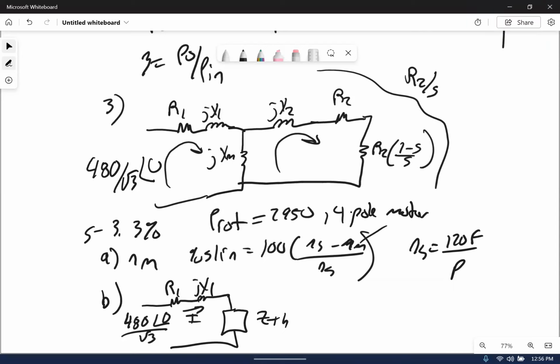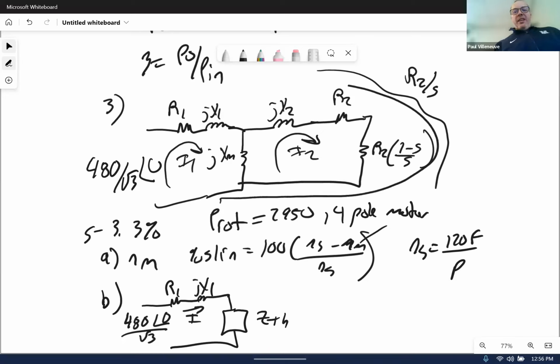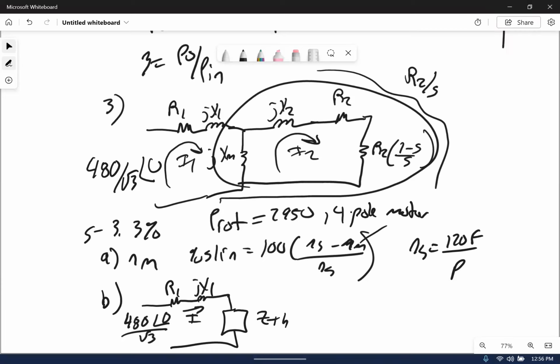Paul, you had a question. Go ahead, Pete, Thevenins. Sorry, yeah, for the Thevenin equivalent on the review, I2 is what you'd be calculating, which from the other diagram, I2 is the rotor current. Yep, that's correct. So with the Thevenin, how are you supposed to figure out the stator current? This right over here, I would convert that to a Thevenin equivalent impedance, right? Oh, okay. So I would do series parallel combinations to do that one.